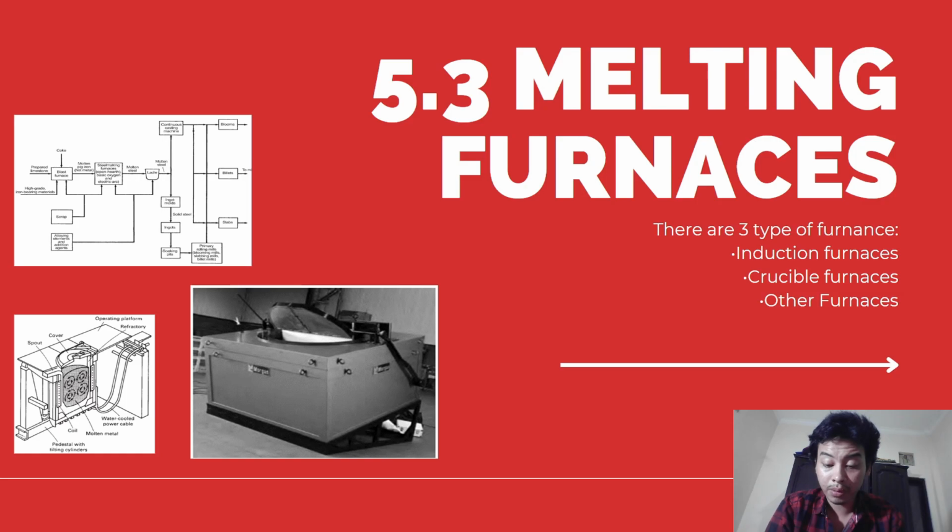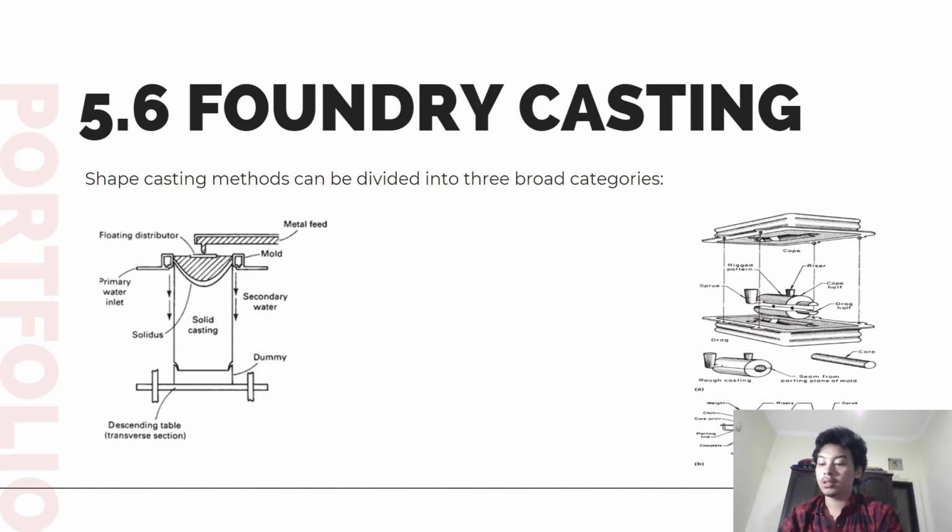Flexibility due to small batch size, fast change of program for different types of steel and alloys, easy operation, low losses of alloying elements by oxidation, achievement of very close compositional tolerance, precise temperature control, low level of environmental pollution from dust output, removal of undesired trace elements with high vapor pressures, removal of dissolved gases, for example hydrogen and nitrogen.